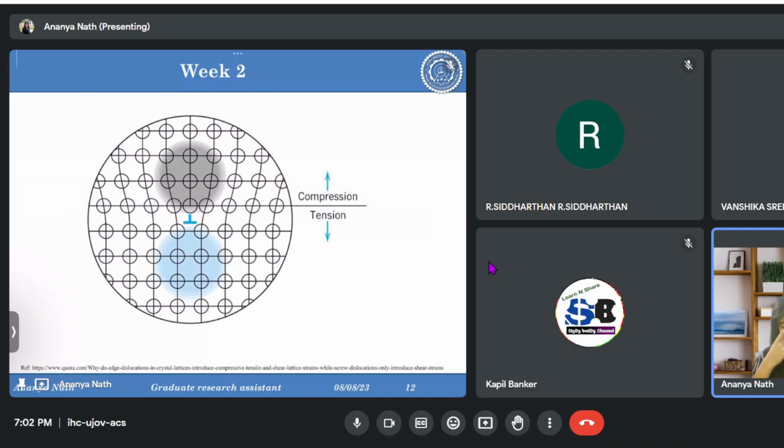So in lecture 1, we got to know about, if you have any doubt in between, just stop me and let me know. So first the modifications were discussed. As I already said, the modifiers are added to change the site for the silicon to grow, so that a long chain silicon will not be formed inside the metal alloy, which can enhance the brittleness many times. To avoid that, we mix modifiers mostly with the Al-Si alloys.